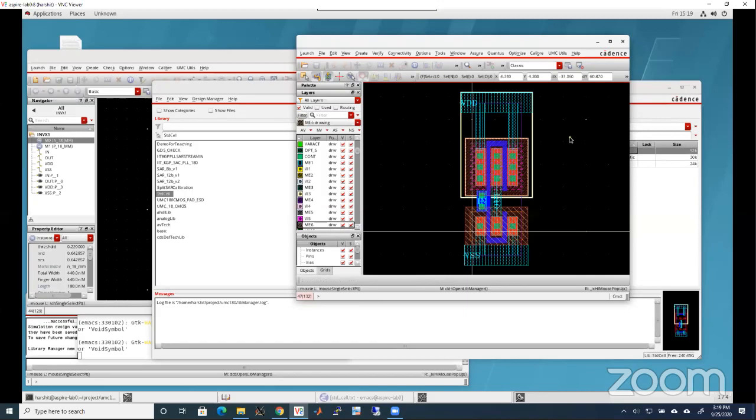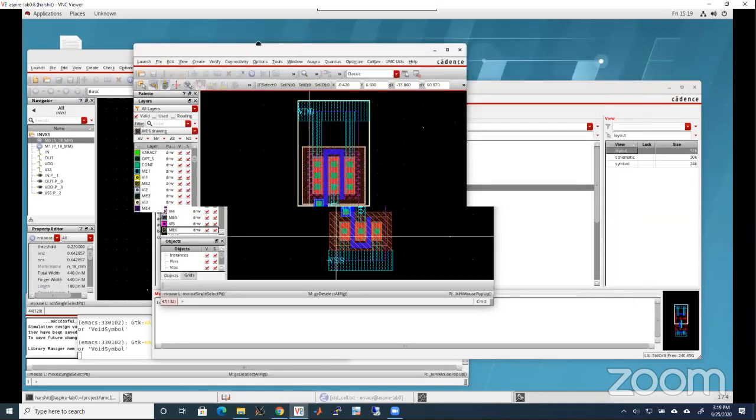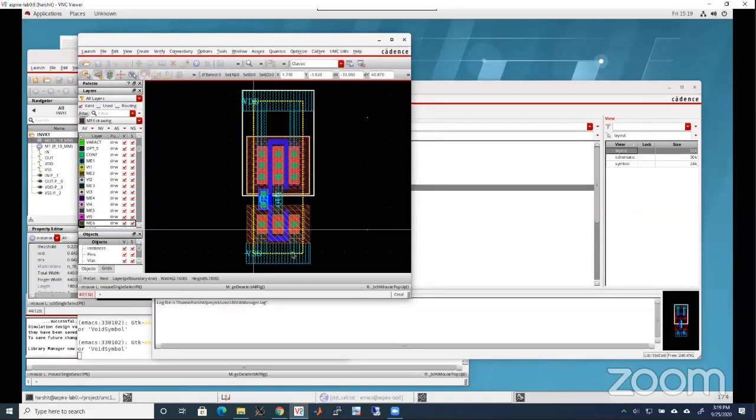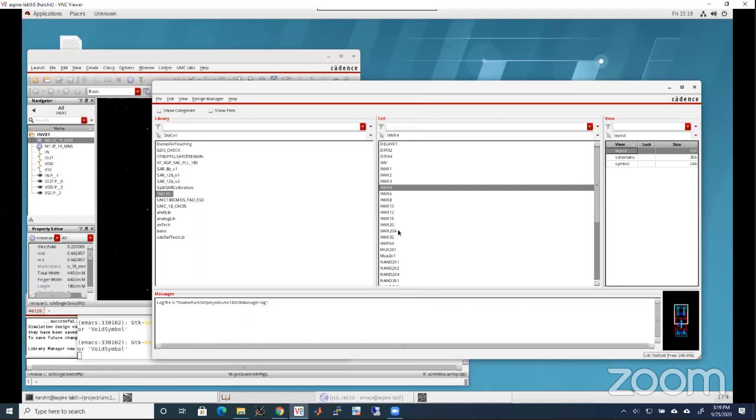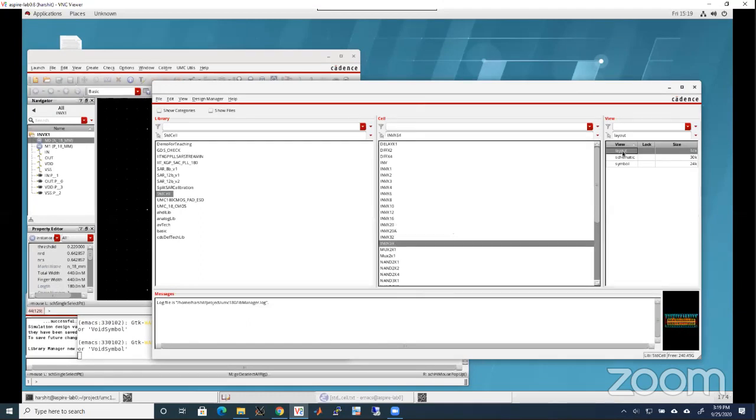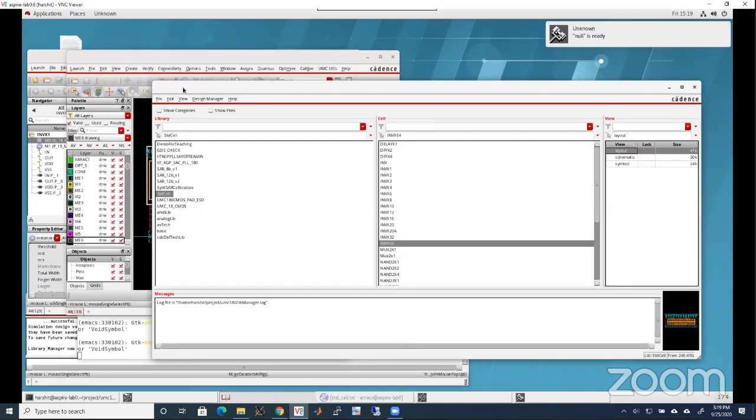Okay, so that means if I have to make NAND inverter 32, my height of the standard cell is fixed. Height cannot be changed. Height of the standard cell is always fixed. That is defined by the number of tracks we can take. Now, if I have to build an X64, what happens if the height is fixed?